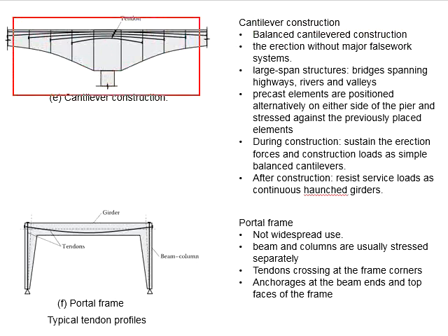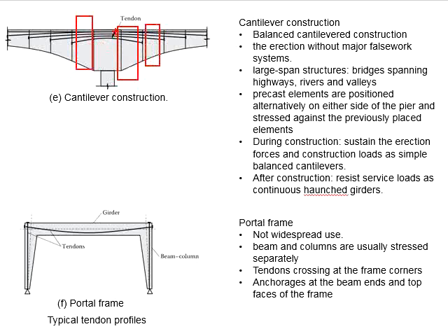You see this kind of construction normally for the applications of bridges, where there will be segments of precast members being installed one by one in a balanced manner. The meaning of balanced cantilever is you will have to install these two panels first before you proceed with the next two.